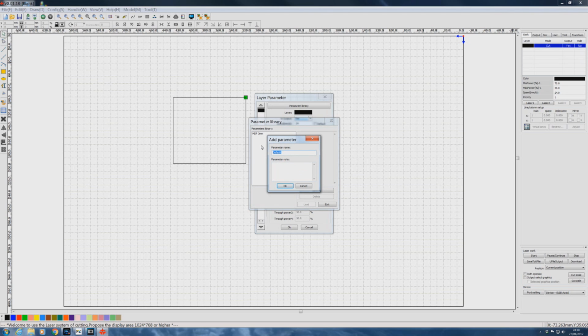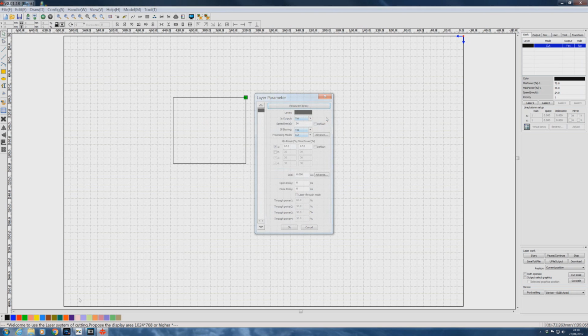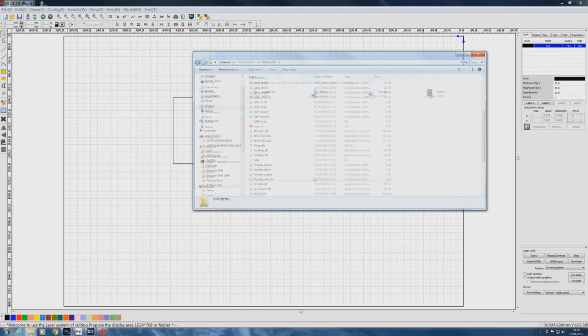But, and here is the but, if you do just this, what I'm going to do, and I'm not going to do it, if I say MDF space 3mm, where have all my notes gone? They're not there. So what you'll do, you'll wipe out the parameters that you've laboriously spent time putting into your library. So you cannot edit the library in this, what would appear to be a fairly simple and logical way. Cancel. Cancel. We've got to go back to this file again.